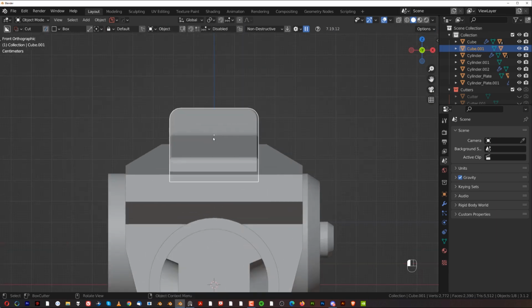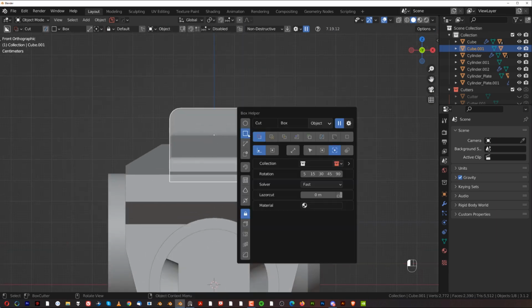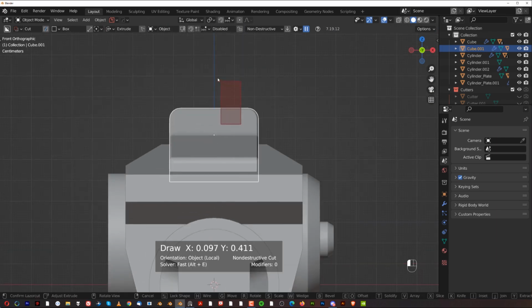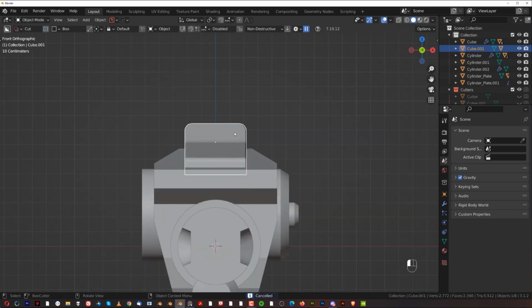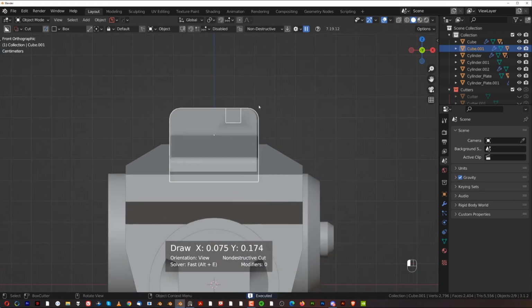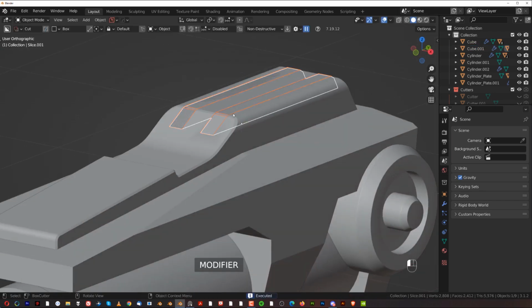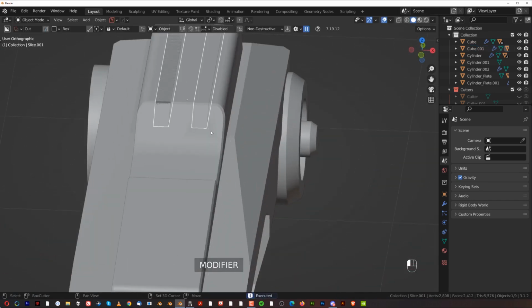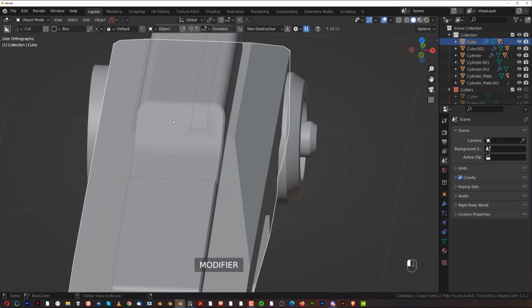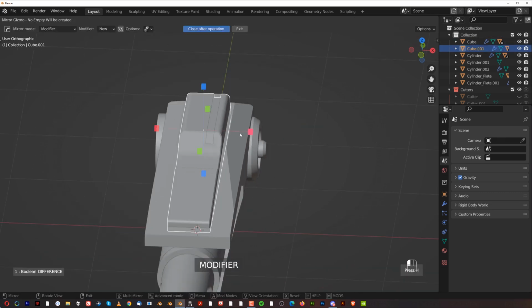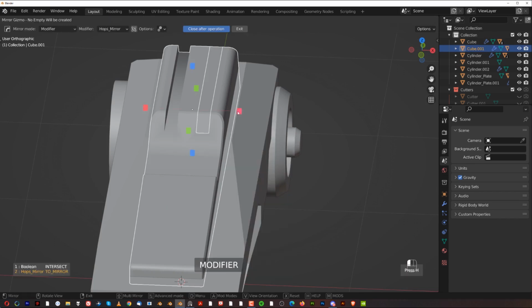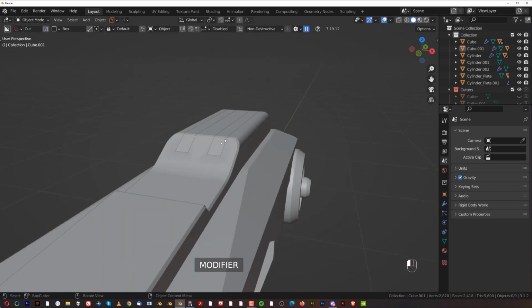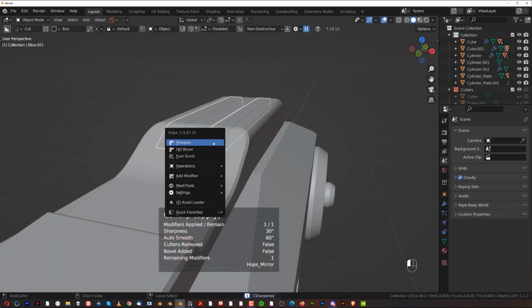Cool. And with this one, we could create some new cuts in here like this. So Shift V and View Align Ortho. Run some cuts here with hard ups, mirror to the other side. Mirror this and mirror this one. There we go. And we can sharpen both.